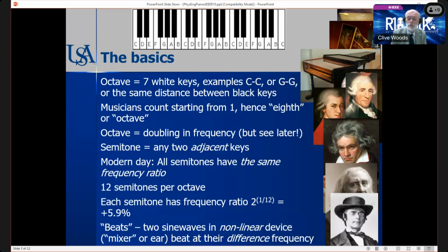And those of you who know about radio design will know that on the front end of every radio set there's a mixer circuit that takes the broadcast signal and mixes it with an internal signal, and that mixer stage is non-linear, because what you want to get out of that is the difference frequency, or what they call the intermediate frequency in radio terms.